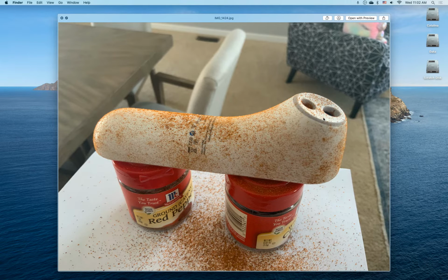This is kind of a low-key process, but from my experience over the years, this actually works really well. If you do not want to use this process because it can result in slight grain in the mesh, you can also buy a can of dry hair shampoo. That works wonders, but the can is also $8, so it's not that cheap. Instead of the can of dry shampoo, let's say you have a glossy black object you would like to digitize, you can also use cornstarch and sprinkle it with a sifter or a strainer over it.